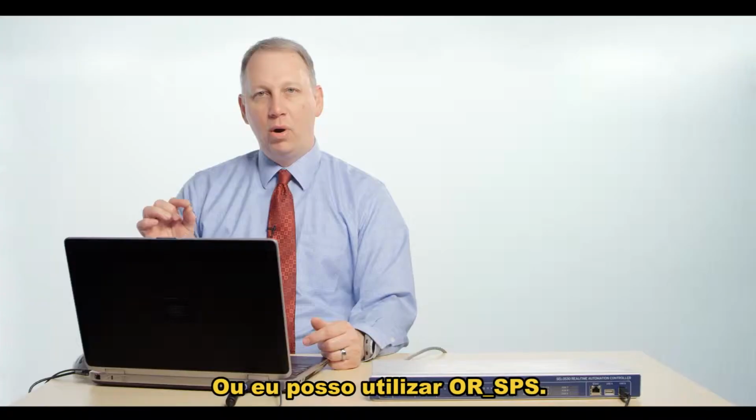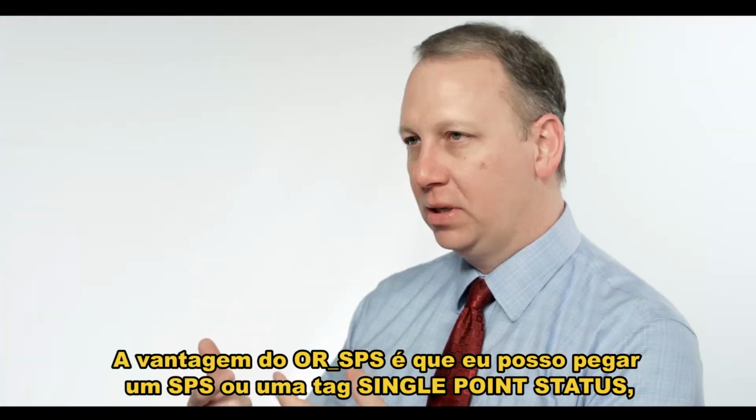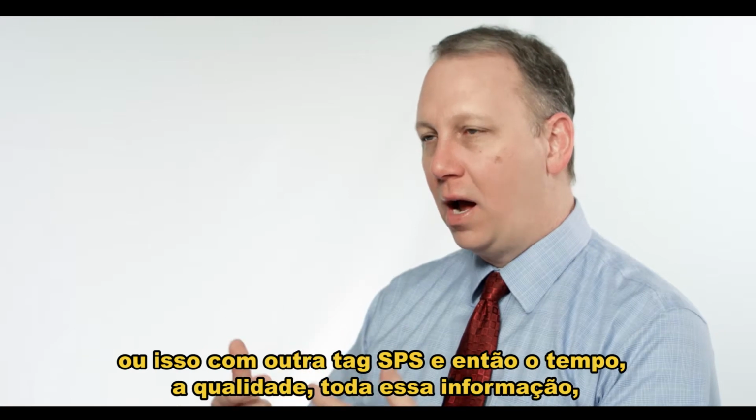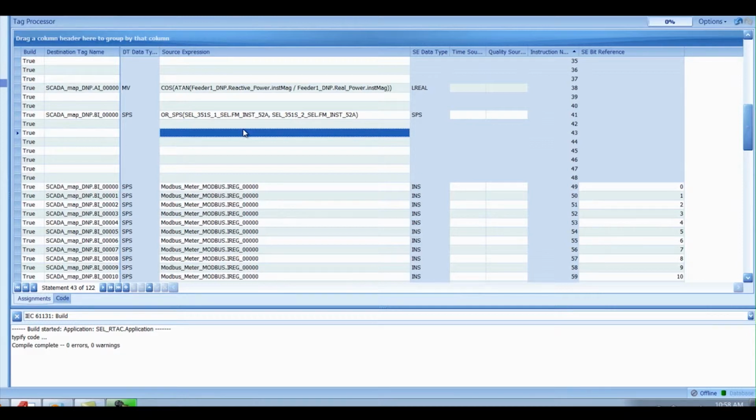Or I can use the OR SPS. The advantage of the OR SPS function is that I can take an SPS, or a single point status, tag and OR it with another SPS tag, so the time, the quality, all of that information stays intact and gets delivered to the SCADA tag, as you can see in this line.